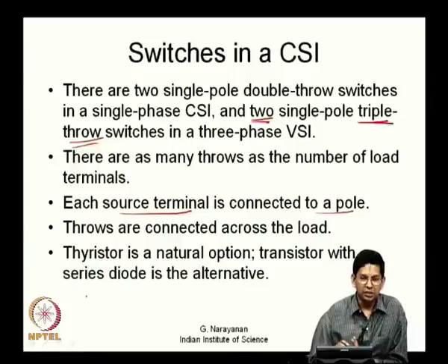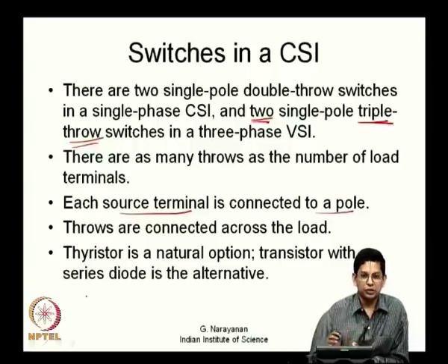Like we saw DC to DC conversion, where we had to step down or step up, buck converter and boost converter, today what we saw was DC to AC conversion. The DC source may be available as a voltage source or current source, and if it is available as a voltage source, what we want is the load voltage should have plus V or minus V applied across it or 0. Similarly, current source should be capable of injecting plus I, minus I or 0 through that.